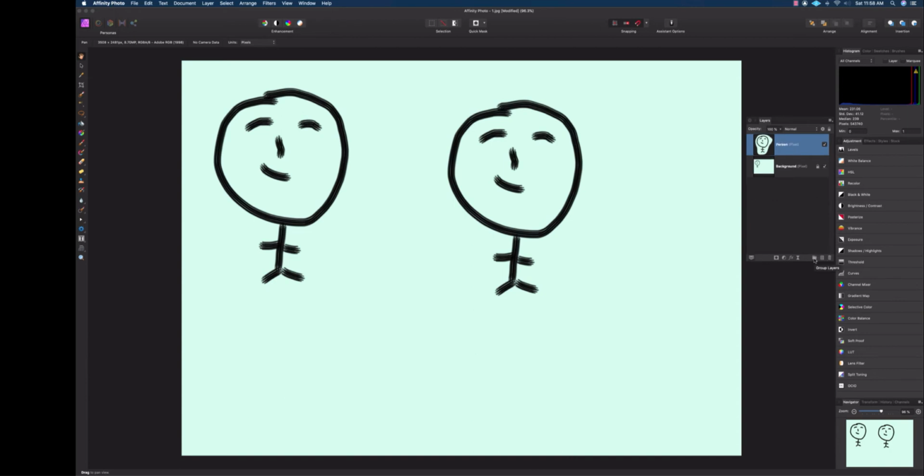And the other thing we could do is group our layers. So if I hold Shift and select both of these layers, then I can go to the Group function and press that. And now it groups these together, which they really should be because I wanted them on one document. And sometimes that's really good because if you have 10 or 12 things you want to group together, you don't want them taking all the space up in your layers panel. So you can just group them. And if you want, you can give that group a name. And there you have it.